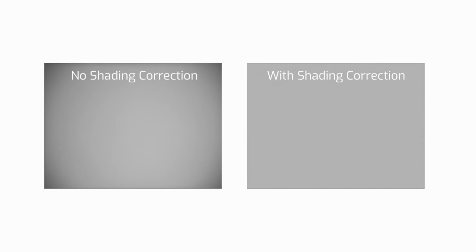This is partly to do with the quality of lens you choose for sure, but it's also because the tiny micro lenses that sit on top of each pixel have the same shape for each pixel. So for pixels that sit farther away from the center, their micro lenses are not shaped differently or tweaked to better capture the light that comes in at a steeper angle. So shading correction can be used to calibrate a gain boost in the edges for more uniformity across the image.